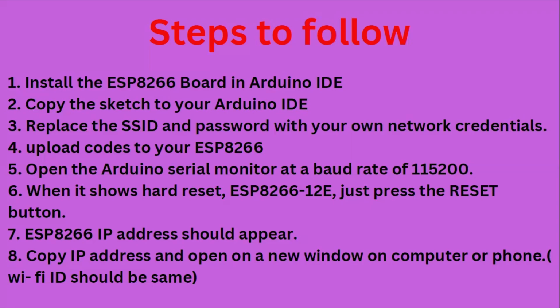When it shows hard reset on the ESP8266, just press the reset button so that it will connect. In the end, it will show hard reset. Okay. The seventh step is that the ESP8266 IP address should appear.